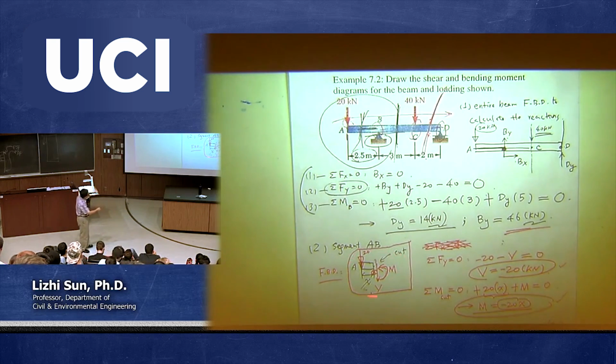So this is a new free body diagram. From this new free body diagram, you're going to collect all the forces in the y direction and set equal to 0. It's guaranteed to calculate the shear force at a cutting point. Okay? So that's why you collect all the forces, you get this one. So this is my part of the solution. We'll leave it there. And we take a moment at a cutting point. You can take a moment at any other point, it's fine. But taking a moment at a cutting point is easier for you.